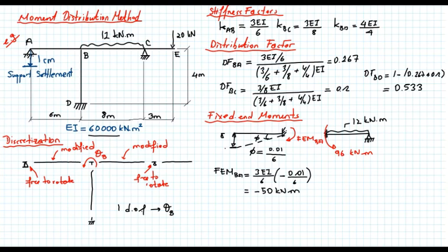I have node C here, and I show it this way because it doesn't matter if it's fixed or flexible, and the moment is always the same. If this is 20, the moment that I see at this end will be equal to 60 kilonewton meters. So this is what I see when the rotation at B equals 0, the no deformation case.